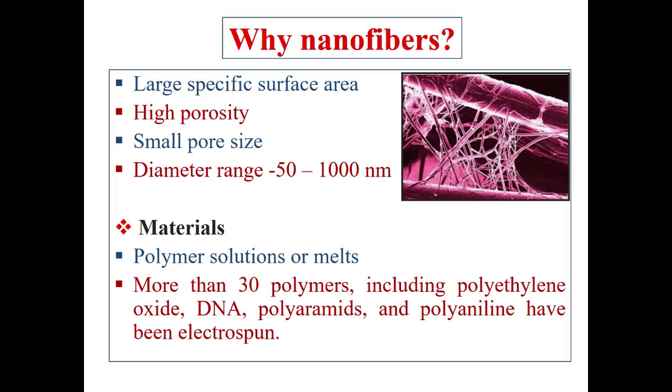Nanofibers have large specific surface area, high porosity, small pore size, and diameter in the range of 50 to 1000 nanometer. The length may be in millimeters or microns, but whatever the diameter associated with that particular fiber, that diameter should be in the range of nanometers, then that fiber is called a nanofiber. Various materials can be used and their fibers can be drawn easily with the help of different techniques.